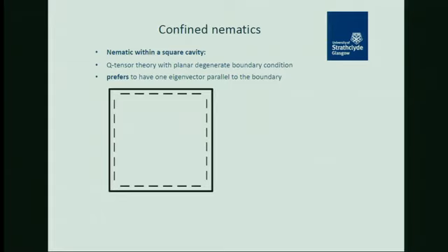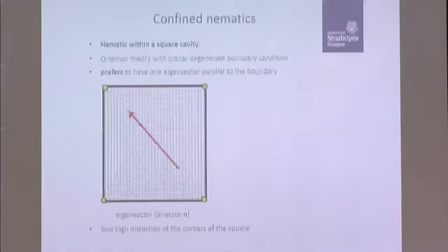If I throw my liquid crystal into there and give it some initial conditions in the numerical scheme, then I get this system here. So here are my little directors, and here's the bulk orientation of my cell, and this is really what we would see optically if we were to form a display out of this. We'd see basically the directors all lying along a diagonal.